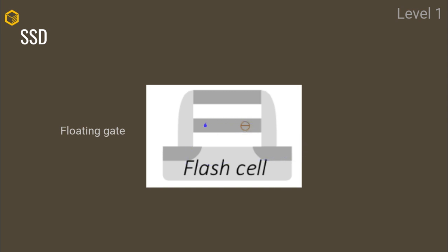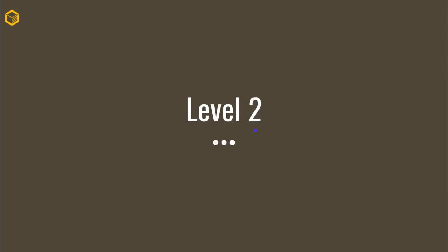And so basically, when you have charges in here, you can consider them to be partially trapped between these two oxides. And the basic idea of the flash cell is to store charges here. So the data you would retain, let it be a 1 or 0, the state of the cell is equivalent to how many charges, so electrons, do I have stuck in this floating gate. So that was a very, very high level overview of a flash memory cell.